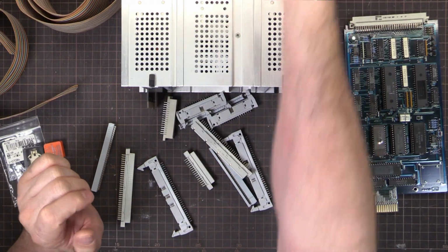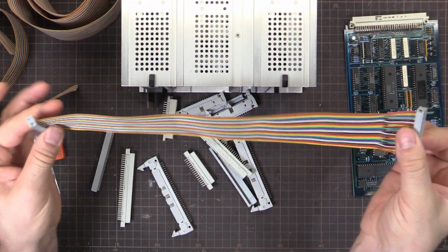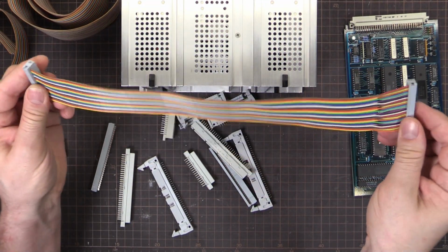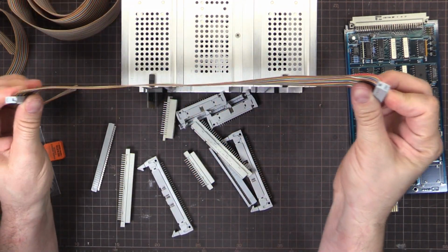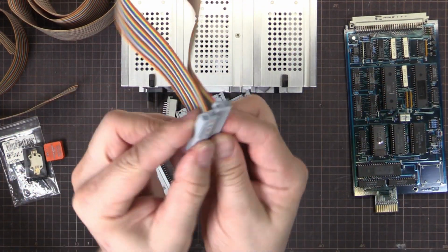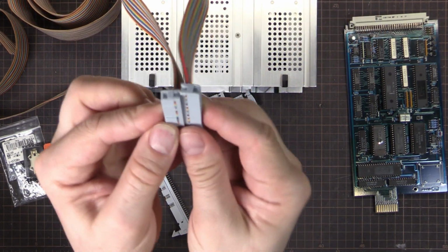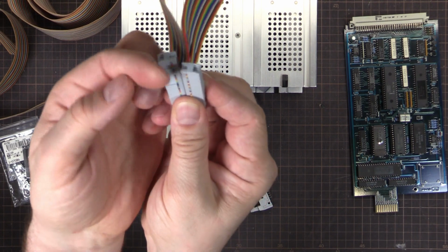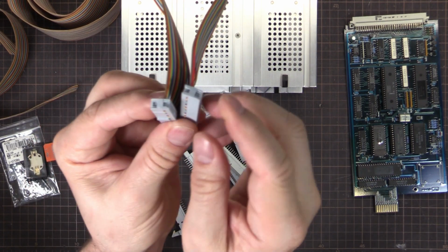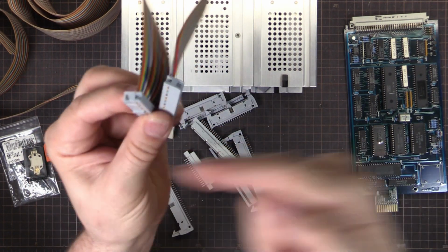So I've got one made here already because I was figuring out how I was going to do it. This is for the smaller connector, and there is a little trick because it needs to be a straight through. So if I bring those two connectors together, we need the top pin towards me on both sides to be like a straight through connection.